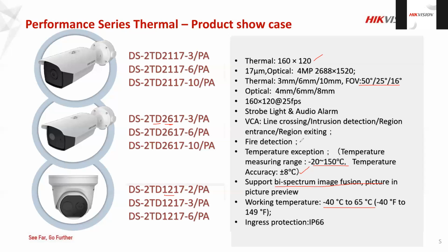So you have the fire detection and the temperature measurement as well. Temperature measurement supports from minus 20 degrees to 150, which is a good range. Also, we consider after maybe 60 or 70 degrees Celsius is fire prone. So then definitely this can be covered through this.